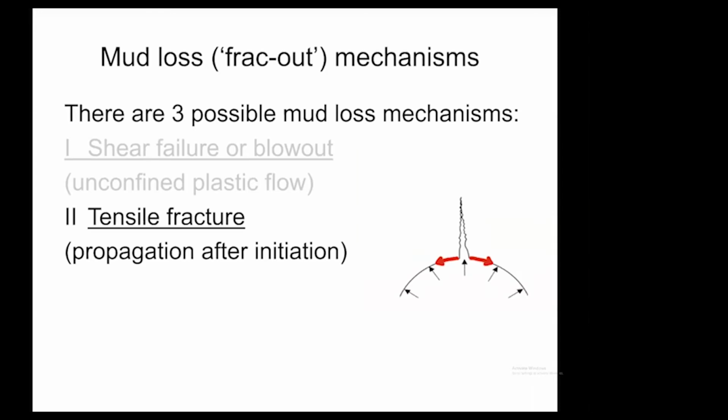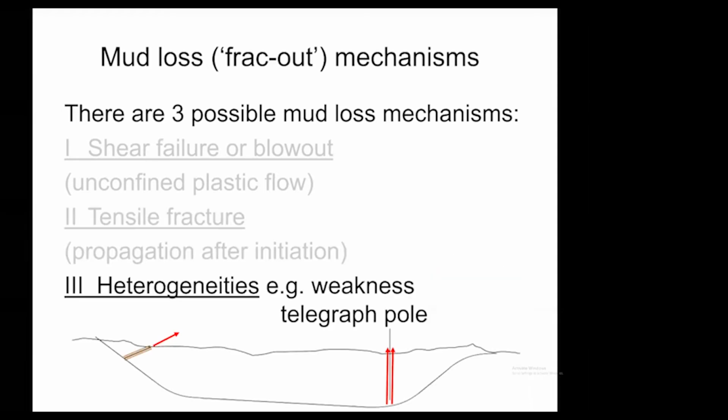We can also get tensile stresses, where the internal pressure within the borehole is stretching the outside circumference of that borehole and leading to incremental tension. And if that incremental tension exceeds the initial compression in the soil, we will get a zone of tension, and soil is very poor at supporting tension, and you'll get rapid propagation of a crack up to the ground surface.